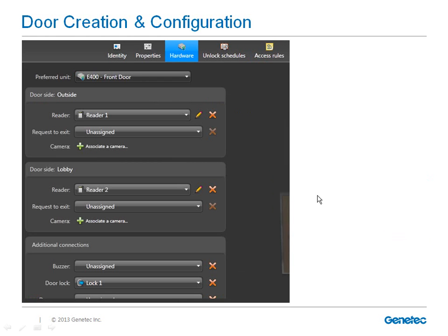Okay, let's take a brief look at using the card and pin for your door readers. Of course, for this kind of situation, you need a reader installed that has a keypad. By default, the reader will accept the card credential or the pin credential and allow access with either one. To see the configuration, click on the pencil icon next to the reader.